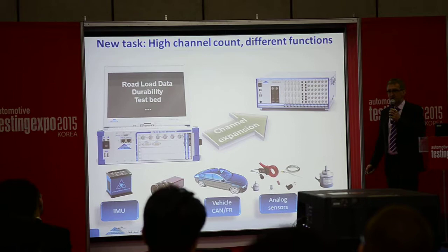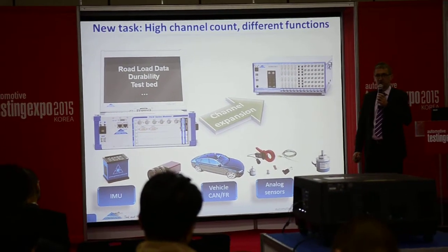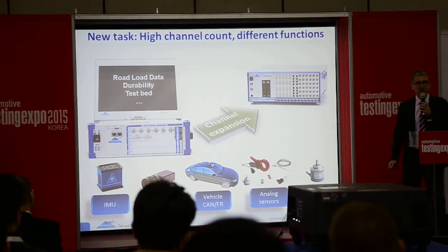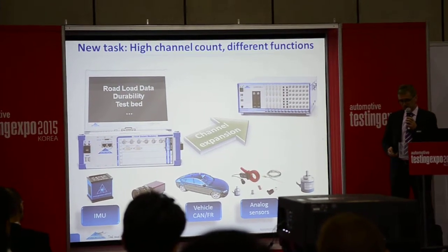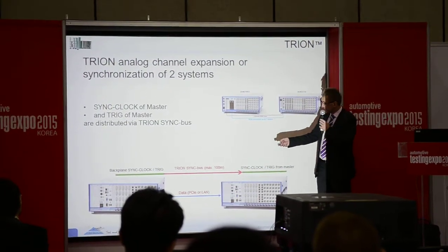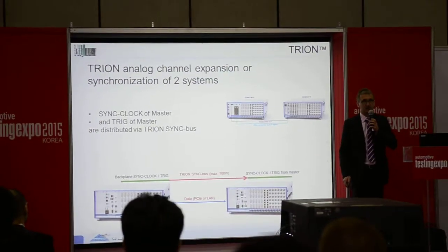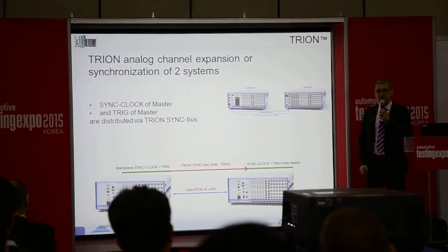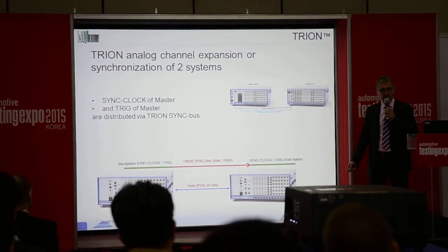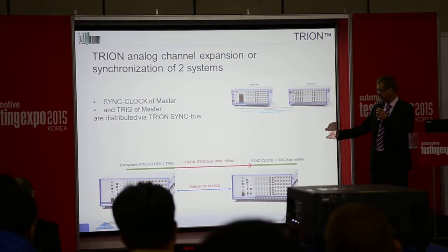Another requirement might be that he should also record video in addition. So what does this now mean to our measurement system and to the synchronization architecture? Remember, in the single system we had the backplane with the sync clock and the trigger to synchronize all the modules. Now, since we add a second chassis or a complete second system, we need to take this and distribute